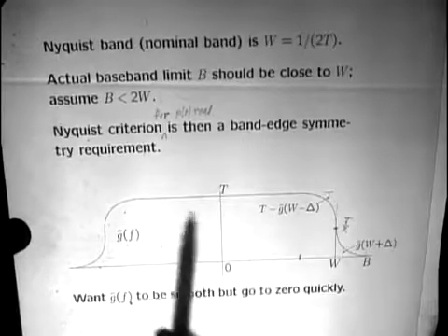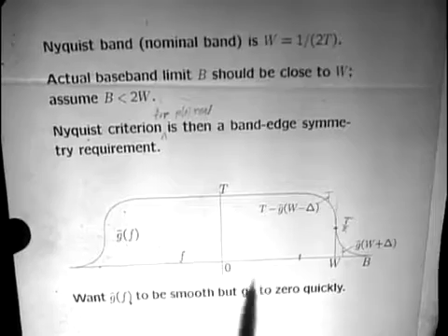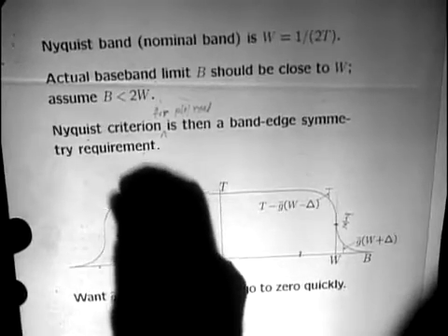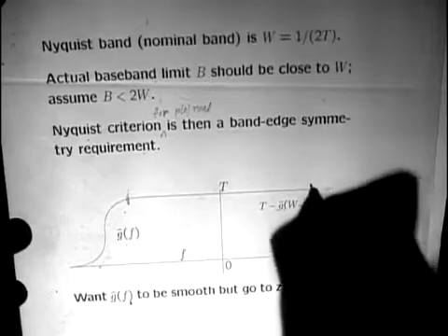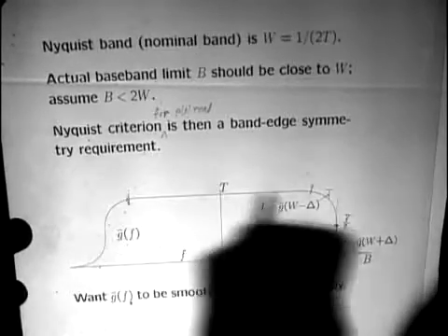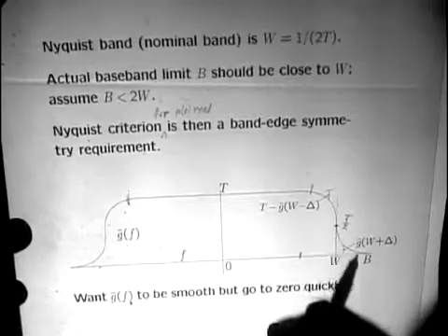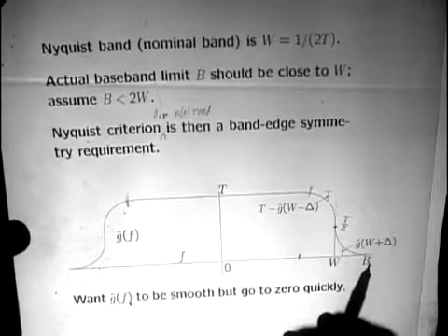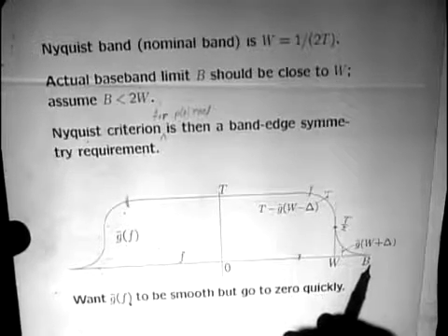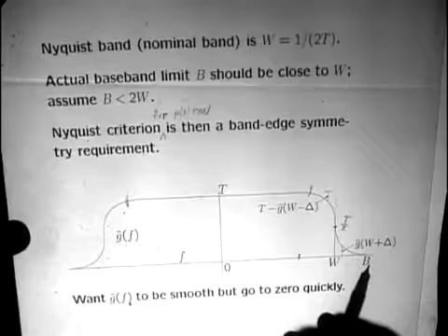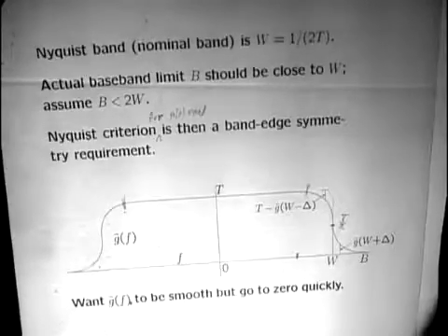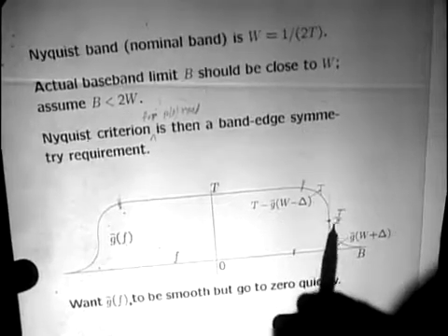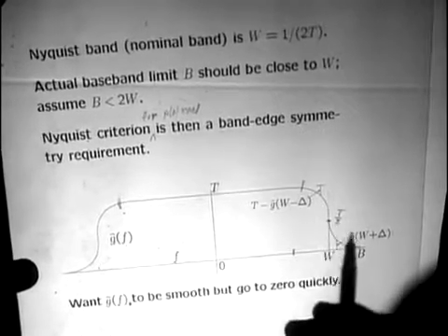So they design these filters, which are raised cosine filters, which over the band here are flat. Over this band here, from here to here, this is a squared cosine analytically, and a squared cosine is just the same as a cosine which you take and displace up, so it's centered right there.